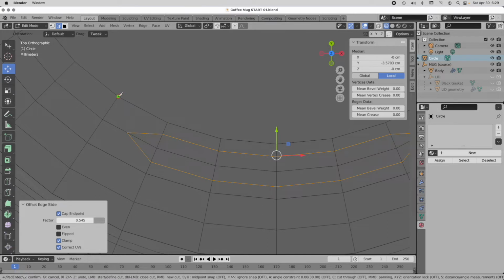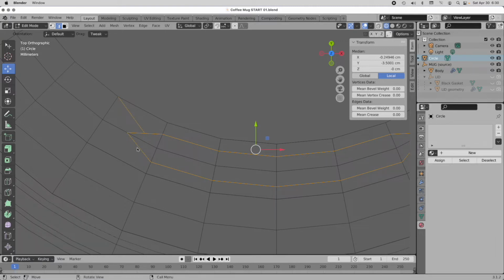I'm going to snap to that vertex, draw over to this edge, but I want it to snap to the center of the edge, so we're going to hold the shift key and click. I actually don't want it to connect right in the middle there, so I'm just going to hit the return key, press K again, hold the shift key, click, release the shift key, and come over to this vertex and click, and then hit the return key.